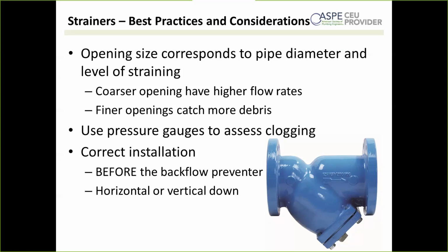This strainer also has a plug on the cover where a ball valve can be installed to help flush debris out of the strainer. So you're getting that higher pressure differential, you can just open the ball valve, and that's going to take out some of the debris. It's a great way to quickly clean the strainer without shutting off water, but eventually these do typically need to be taken apart and properly cleaned.